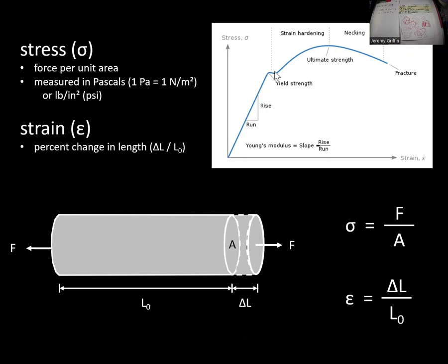But concrete, actually, this graph would end right there. It got snapped, and it would rupture right at this point. So for that reason, I know that this particular graph probably applies to a metal like steel, because metals like steel have this whole extra bit above here, like this ultimate strain, and this rupture at this strain way out here on the diagram. Okay? So concrete, bam, breaks right here, and then metals can stretch a little bit more.